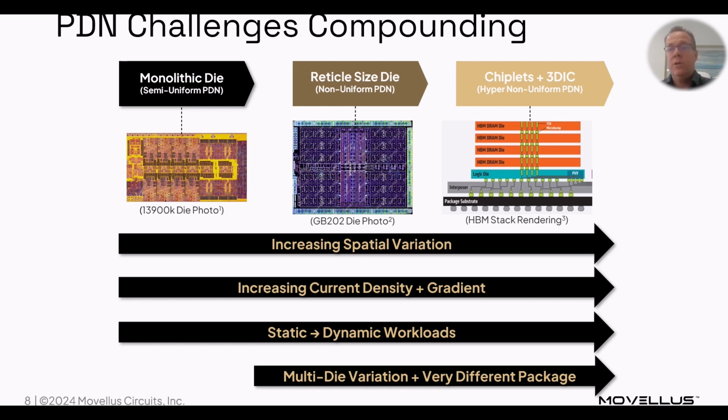Finally, if you package multiple die into a chiplet environment, a multi-chip package, either laterally connected or stacked, what you find here is the environment that you use to characterize your die on the tester is drastically different than the environment that's actually being used once you package multiple die into a chiplet. So having voltage visibility at each of these scenarios, especially at the chiplet post-packaging time, because the voltage that's being applied to the transistor in a chiplet environment may have had to go through through-silicon vias, packaged dies, may be generated by one of these dies. So what you tested for on the tester may not be what the transistor is seeing in the field.